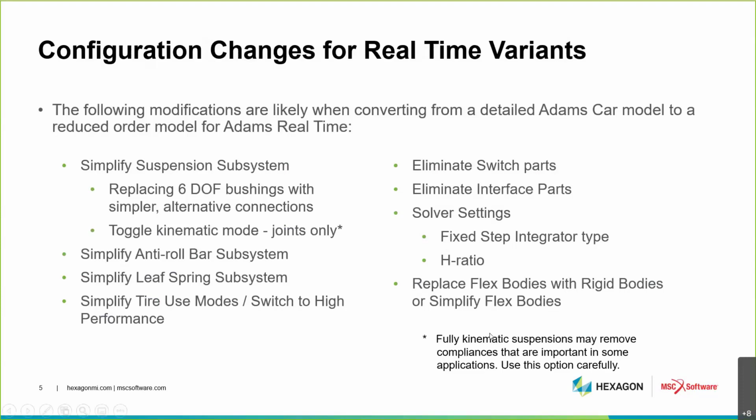And it's worth pointing out that when you use the kinematic mode, you may be removing compliances that are actually important for getting the proper behavior in some applications. So this can be seen as a little heavy-handed. You want to be judicious about using this option.